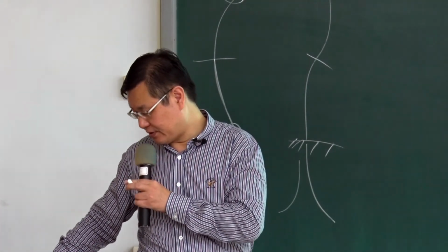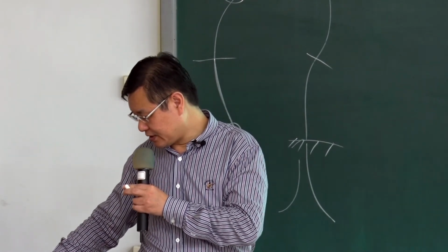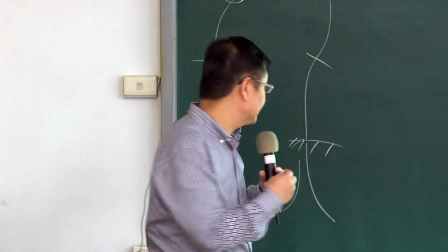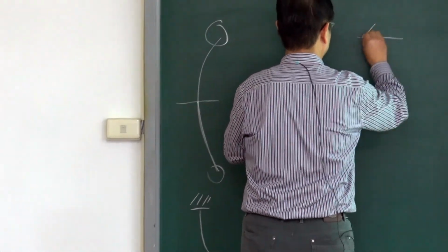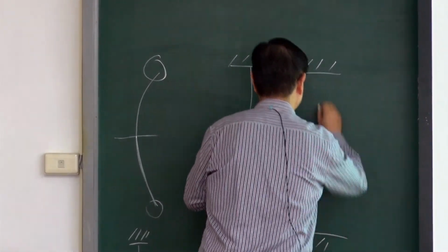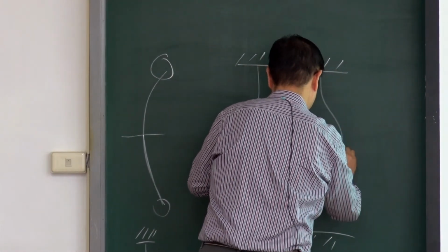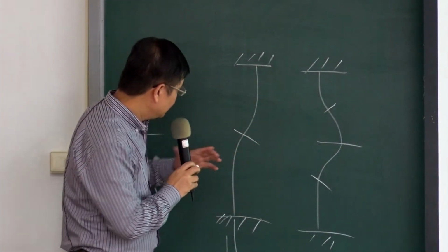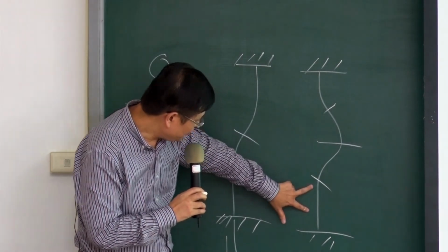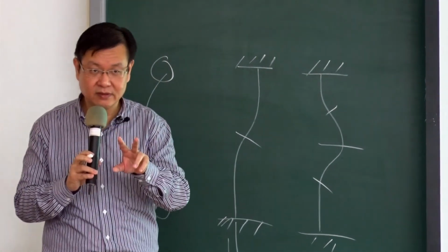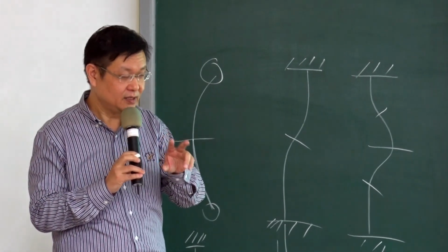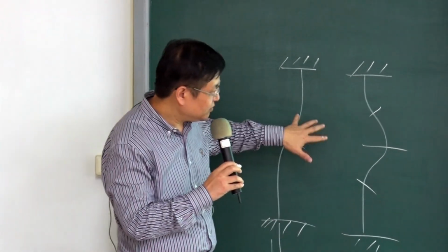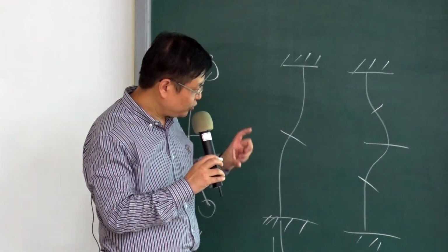The third one is a little bit difficult. You need to do some calculation. The first one, you can cut this piece into 4 pieces: 1, 2, 3, 4. Each one is like one cantilever beam, but the length becomes 1/4, becomes shorter.